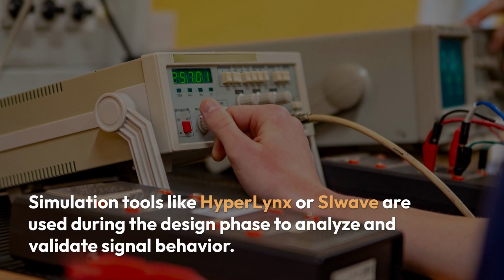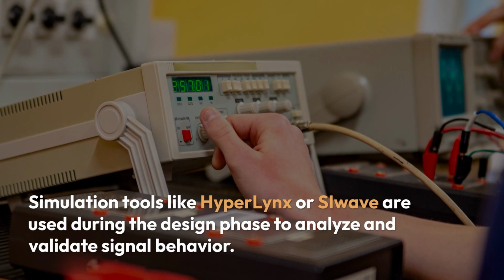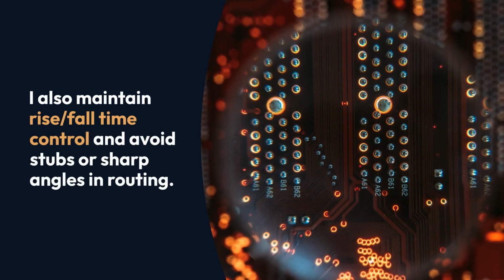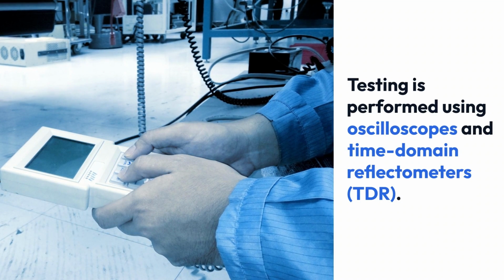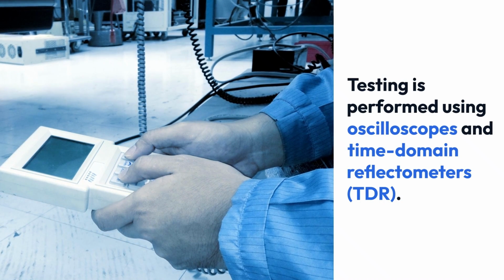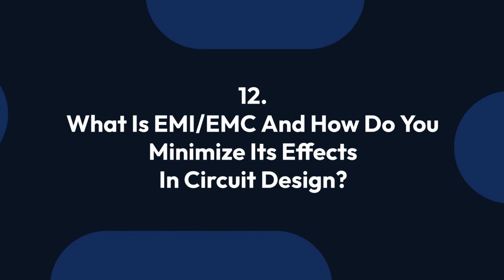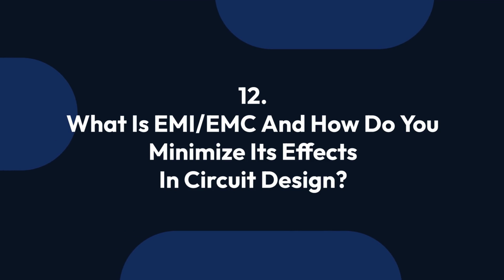Simulation tools like HyperLynx or SIwave are used during the design phase to analyze and validate signal behavior. I also maintain rise/fall time control and avoid stubs or sharp angles in routing. Testing is performed using oscilloscopes and time domain reflectometers, TDR. 12. What is EMI/EMC and how do you minimize its effects in circuit design?